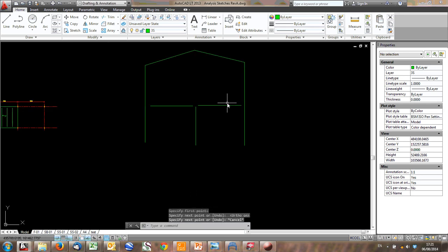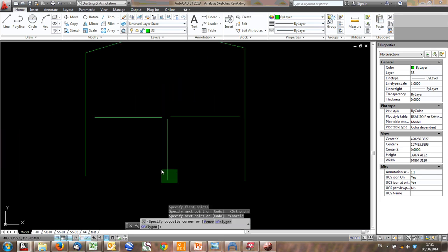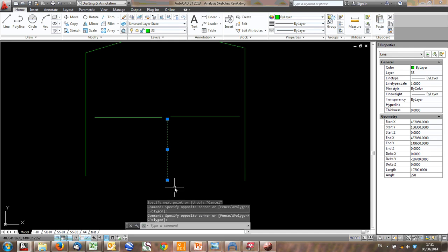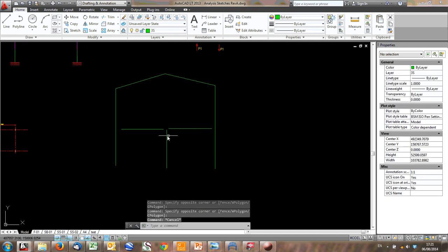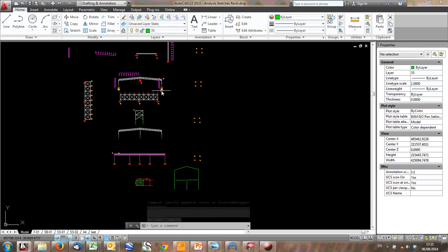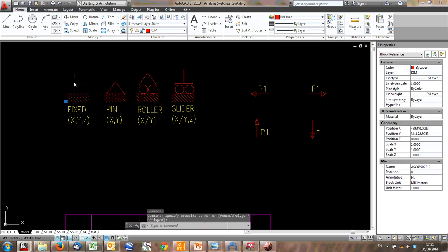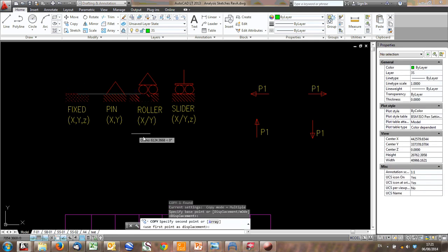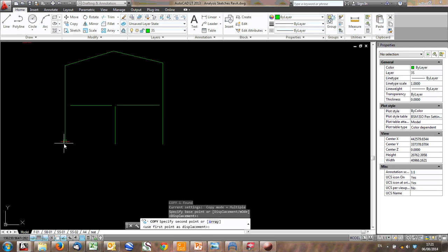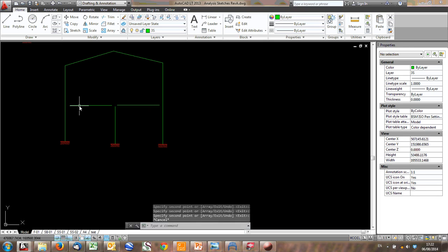If you analyze this, what do the supports look like? Where do you find support from? Well, obviously, you've got some fixed connections or pin connections, depending what your fixity looks like here. So let's say we're fixed. Let's say we are able to carry the fixed load here. Moment here. So we've got fixed support, fixed support. But one thing also, remember, this is a concrete deck once it's crossed, so this becomes very stiff.